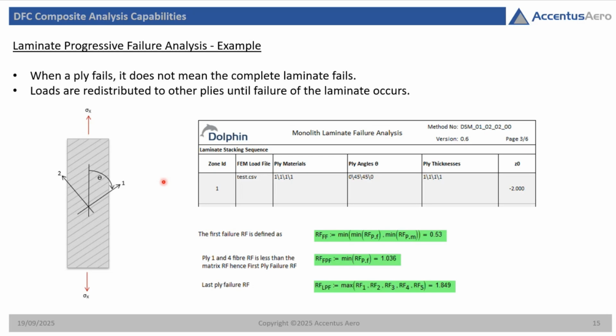So you actually don't need all those other plies for this specific case. So this is the principle of progressive failure. The other add-on to this is you can use this to optimize your ply layup. You only need fibers in the direction of the load for that specific load case. So this is how you can optimize your layup for your structure.